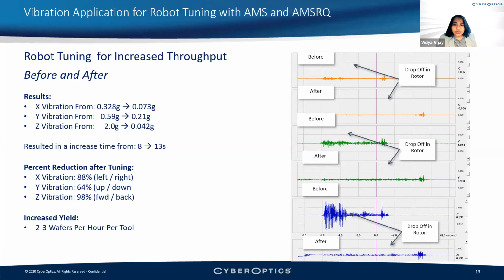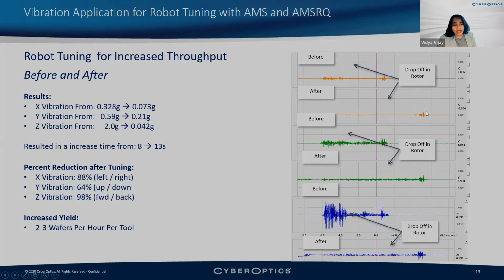All of a sudden, you are usually okay in the process with this amount of vibration, but there are huge amounts of vibration. Then maybe it's the bearings or something else has gone bad. It's not just the tuning. There is probably more need before things fall apart, like preventative maintenance can be done.